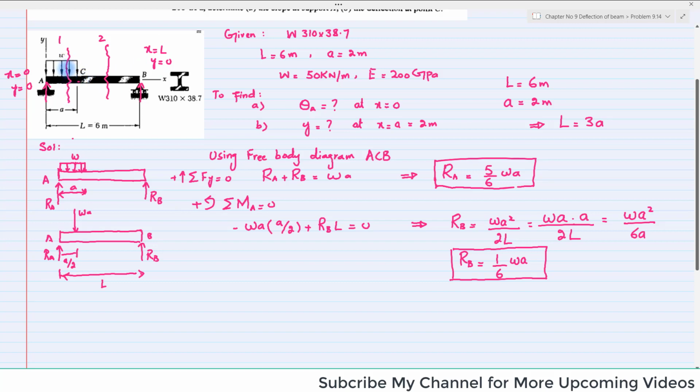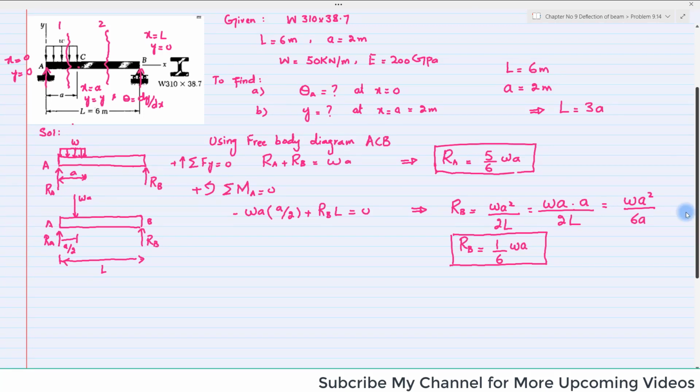As we are interested to find out the slope and deflection at point C, at x is equal to a, we have y, which is deflection, and theta is equal to dy by dx, which is not known. Clear? That's why we are using two portions of the section, 1 and 2, and we will apply the boundary conditions in order to find the unknowns. Clear?